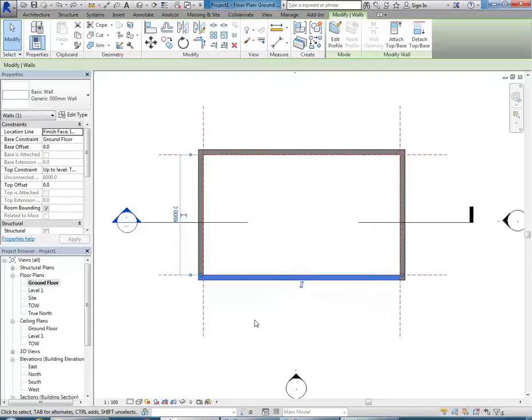So you go off the north side? Oh yeah, Revit's got a setting for true north, and as long as you set it, the sun will automatically come in when you're rendering your perspectives, exactly.